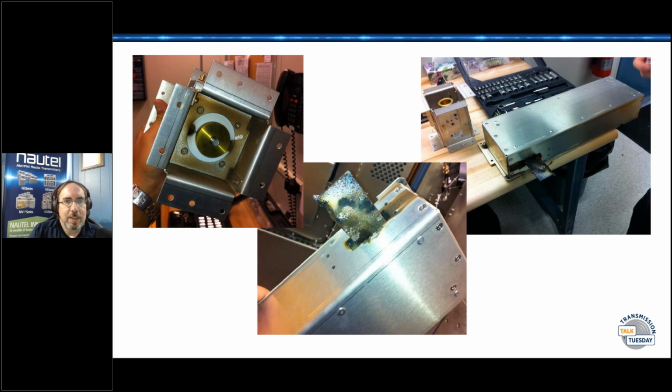Well, I'll preface this by saying nothing is 100%. About the time you think you've got everything down to a science, nature finds ways to totally thwart you. But the two best ways that I've found for keeping snow off of dishes, and granted, most of these are KU dishes in the networks that I've worked with. In Wyoming, we had covers on all of the dishes. They were just 1.2 meter aluminum dishes, and we would put a snow cover over them, and that was for the most part pretty effective. The drawback was they kept getting whipped around in the wind, so it was pretty much a consumable item. You make sure they were tensioned as best as possible, nice and tight like a drum on the dish, but they would eventually rip apart in the wind, so you had to make sure that you would replace them, because one that's damaged is almost worse than none at all, because it can trap all of the snow in your dish.